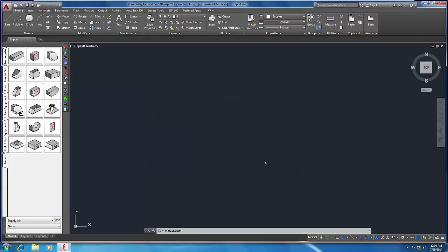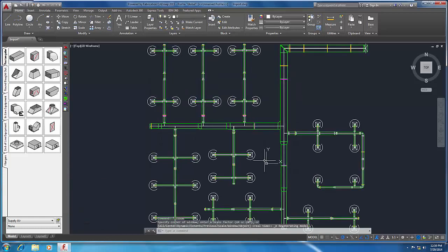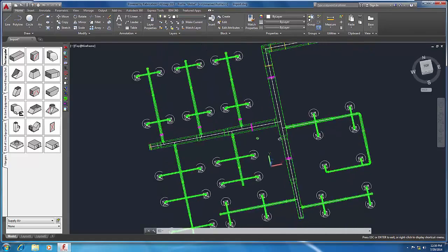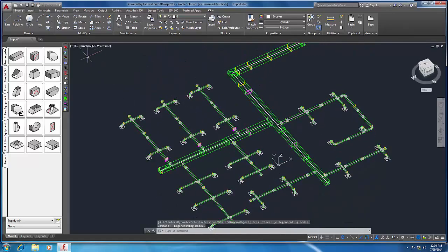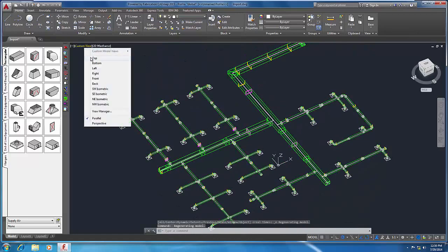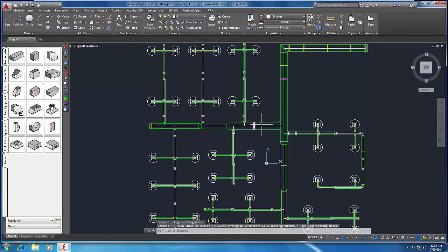The converted Revit elements will appear within the CADmep drawing window. Zoom or pan if necessary to see the newly created items. Change AutoCAD views and visual styles if you wish to see the imported 3D model. Restore your view and visual style if necessary, and zoom in to the central supply duct where the branch ducts appear.